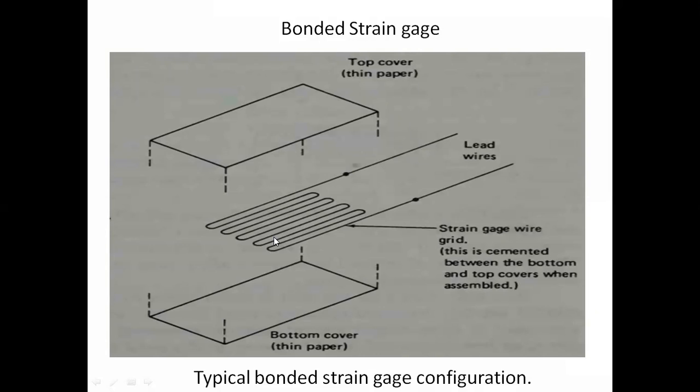Okay, and for that platform below we will place this particular strain gauge. This strain gauge is attached at the surface of the platform, and we will place the material on this particular platform only. When the weight is placed on this platform, the weight will be transferred to the surface of the platform, and below that we have a strain gauge.